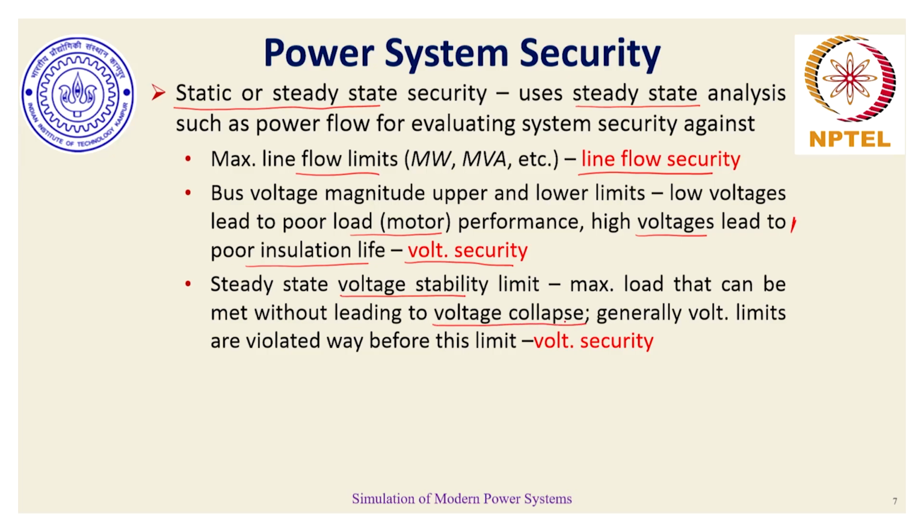If the voltage drop goes up, it is possible that at the source end we have stiff voltage regulating devices, but the corresponding load voltage will be very, very low. So there comes a point that if the load keeps on increasing, the load voltage at the receiving end tends to go down, and after a minor incremental increase in the system load, the network will experience voltage collapse. That means no matter what voltage regulation or reactive power support devices we bring in, when the load is close to its voltage collapse capacity, the system will face a blackout event or a cascading event.